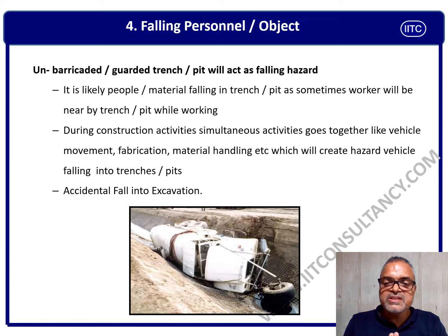During construction activity, as you know, there are SIMOPS, simultaneous activities going together, like vehicular movement, fabrication activity, material handling, and housekeeping, and whatnot. So this SIMOPS activity may carry additional risk along with excavation, because if it is unguarded, unbarricaded, definitely people will fall. So it is our responsibility as a supervisor, as a construction manager, as a safety engineer, to ensure that each and every excavated part must be barricaded and must be hard barricaded.